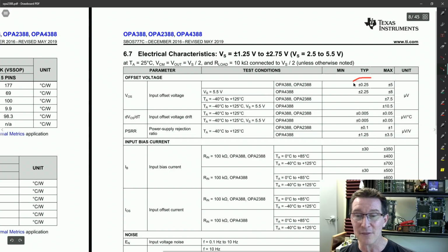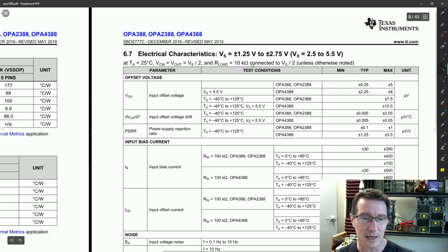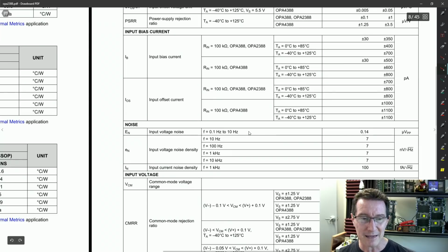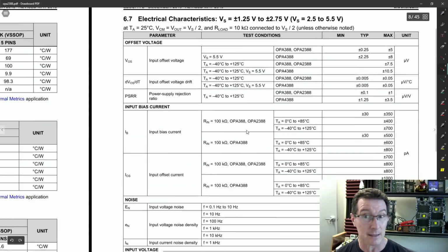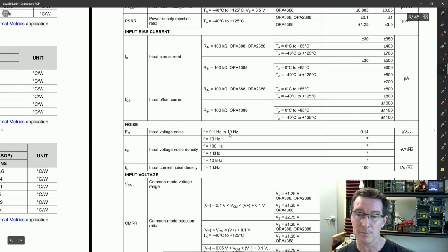Because once again, if we had that, and it was typically around that, and we used it with a 4.5 digit meter, you'd get plus minus 2.5 least significant digits flapping around in the breeze. Well, they're not flapping around in the breeze, you could null it out. But anyway, we're after a precision op amp, so not quite as good. But if bandwidth mattered, if that could give you some benefit over somebody else's product, then you might go, hey, I'll sacrifice some of that offset goodness for bandwidth.